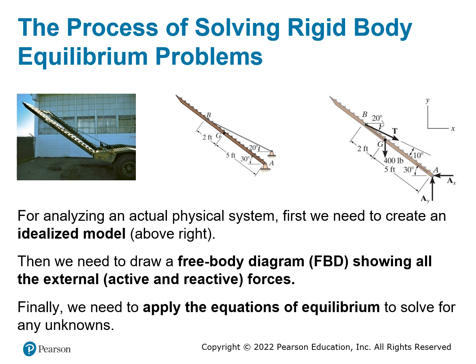So let's go back to the previous problem that we just saw. Again, you have this ramp and you have a pin at the bottom here. The pin is the key that will determine how you can solve the problem, because you need to identify for a pin, what can a pin support? And we're going to see a different kind of support. For the pin support, you're going to have an X direction force and a Y direction force, but you're not going to have any moment as a reaction force.